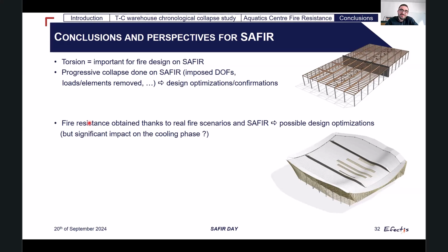And on the perspective, a bit more for Thomas and Jean-Marc for SAFIR, it would be interesting to have a SAFIR explicit solver, because when dealing with such complex 3D structures, when one element fails, it is a bit complicated to see what happens after. It could be also interesting to have the torsional properties updated in the SAFIR code with the temperature evolution. It will also be interesting to have a mechanical restart in SAFIR, because it would spare an extensive amount of time when we have to do iterative process like the one in the Codifab project.